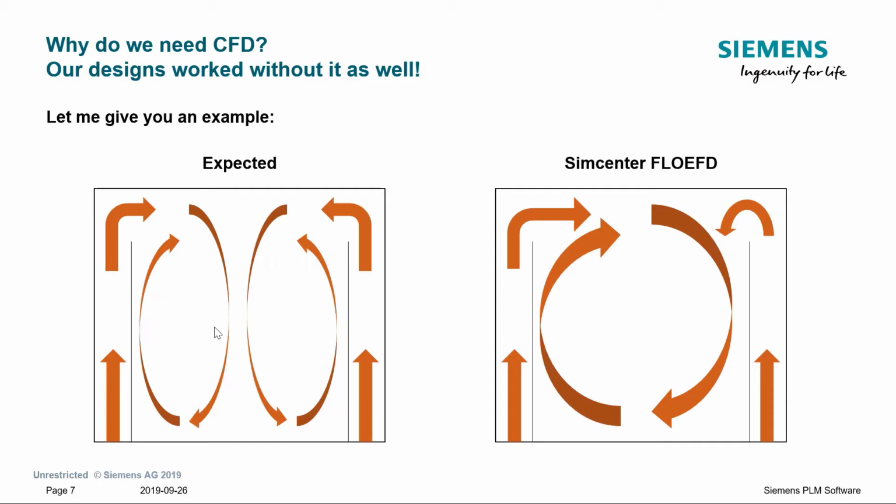So they thought the simulation is wrong because this is not natural. It's a symmetric room, it should have symmetric vortices in there. But they said, okay, let's do a test. So they put in some poles with warning tapes attached to them, so they can actually see how the flow is circulating in there. And what they got is really this. They didn't expect it. They expected to have a symmetric flow as well, so two vortices in there. But reality is sometimes behaving differently.